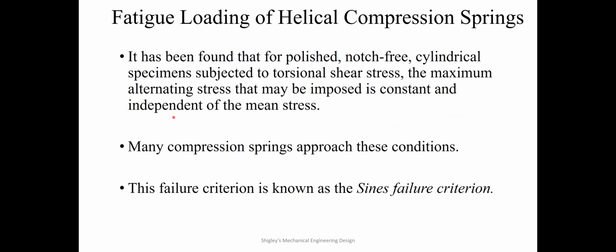Okay, and yes, we find that for the polished notch-free cylindrical specimen subjected to torsional shear stress, the maximum alternating stress that might be imposed is constant and independent of the mean stress. And many compression springs approach these conditions. And this failure criterion is known as the Sines failure criterion.